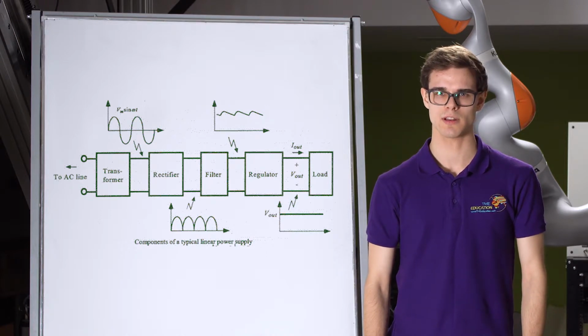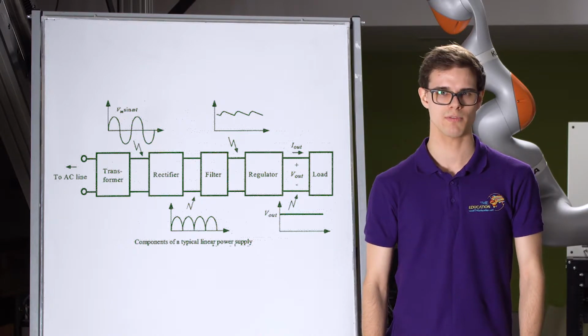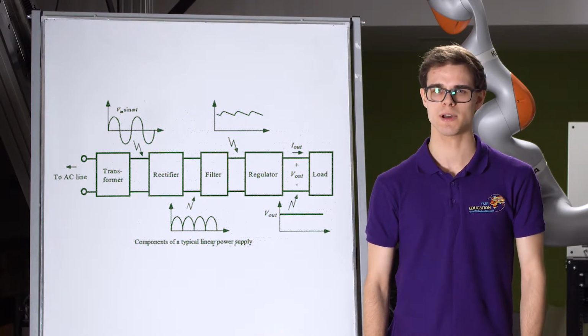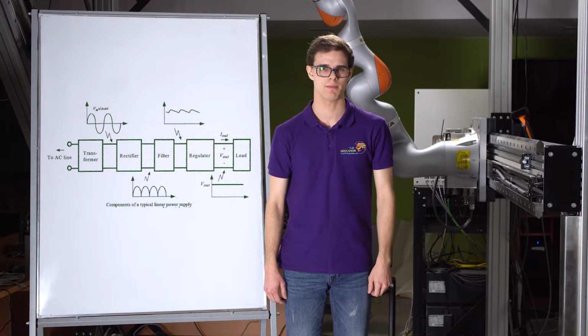which changes current from alternating to direct. Third block is ripple filter, consisting of large capacity capacitors, which store energy in order to maintain voltage and low ripple level. If the power supply is stabilized, it also has a voltage stabilizer to reduce load and temperature influence on the voltage level. These power supplies are relatively cheap and simple, but they are also heavy and inefficient.